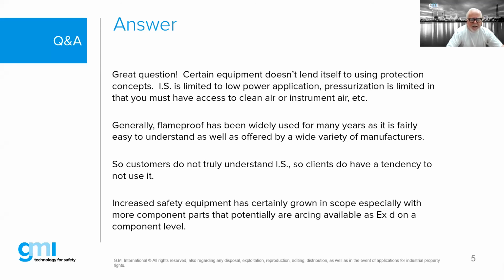So people understand it. I think with increased safety, part of the issue is that we cannot put any arcing or sparking inside of increased safety equipment without further protection, meaning that if we wanted to put a relay inside of an EXE enclosure, that relay would have to be certified. Or if we put a contactor on the inside of an EXE enclosure, that contactor would have to be EX certified. So EXD allows you a lot more flexibility. It allows you to use general purpose equipment in a hazardous location.